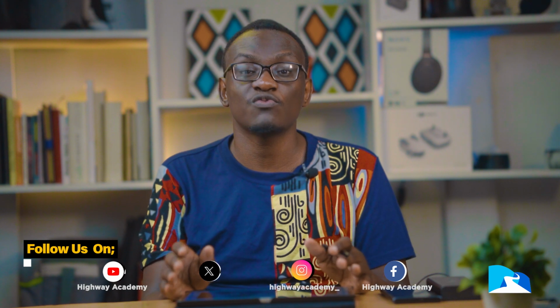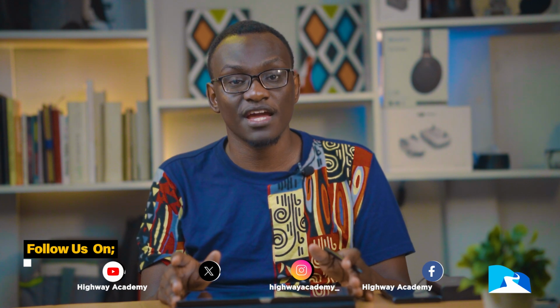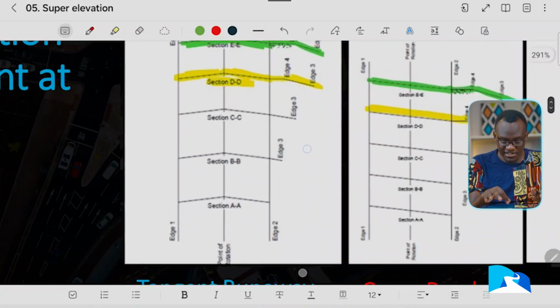In this lesson, we talk about super elevation. Now, super elevation is a much more complicated topic, but what you always do when you're designing junctions is make compromises. There are things you have to do. You have to understand the super elevation. You have to understand what the nearby surroundings are before you super elevate. It may not make sense to super elevate a junction if the nearby surroundings are going to suffer. But at the same time, you need to consider drainage. So how do you super elevate a junction?